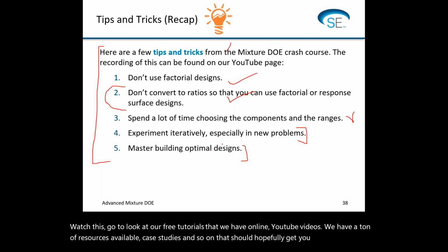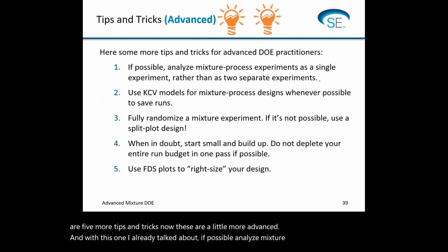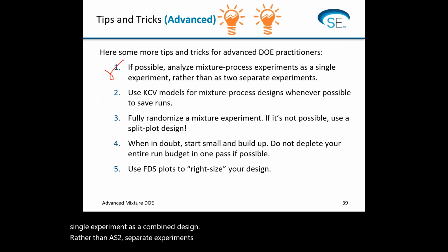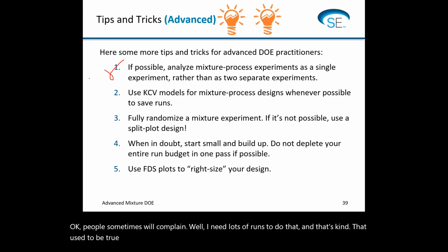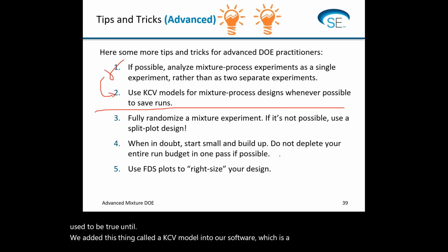Now, here are 5 more tips and tricks. Now, these are a little more advanced. And this one I already talked about. If possible, analyze mixture process experiments as a single experiment, as a combined design, rather than as 2 separate experiments. Okay. People sometimes will complain, well, I need lots of runs to do that. And that used to be true until we added this thing called a KCV model into our software, which is a special model for mixture process designs.